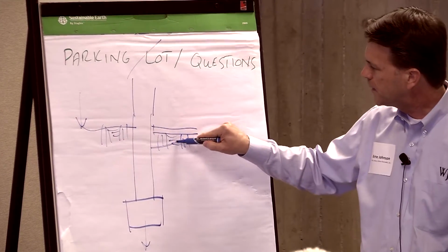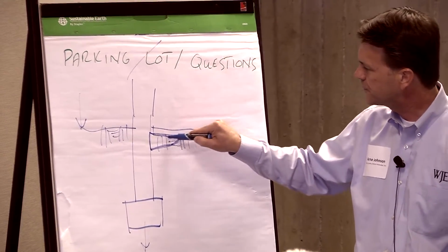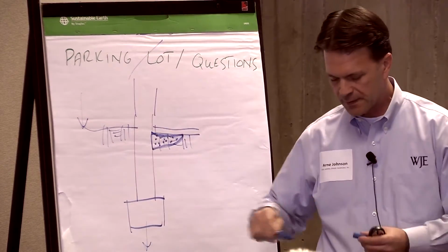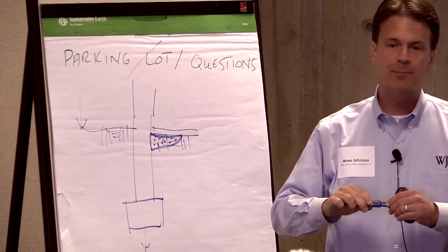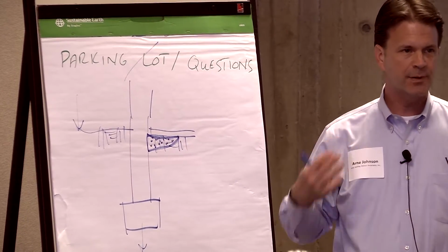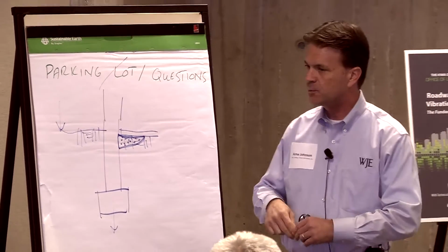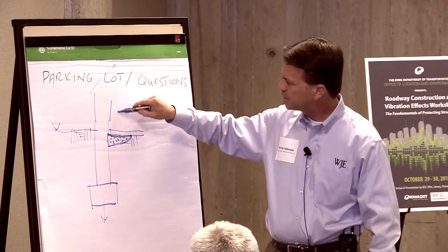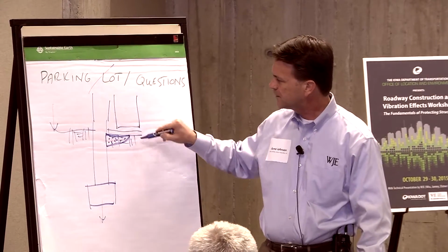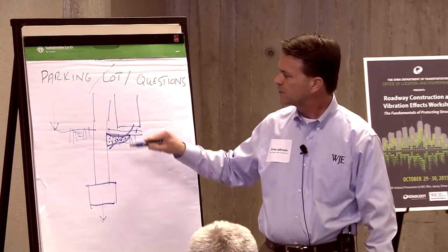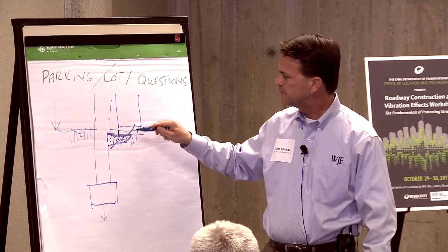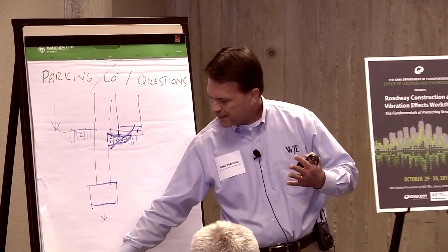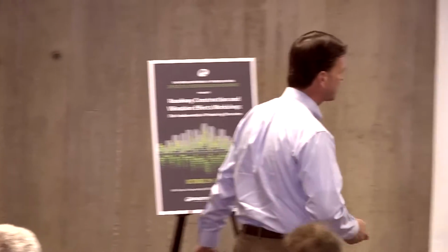I would be concerned about potential voiding, as a structural engineer, right there. There might be a void that developed due to foundation settlement, you see? And that might not be visible. So an experienced engineer is going to think about these kinds of things. It's indirect damage, but it's damage. It needs to be fixed. If they come and put some heavy shelving here in the future, your slab might crack and fall down. So we would do something like mud jacking, void filling, that kind of thing. So that's indirect damage.